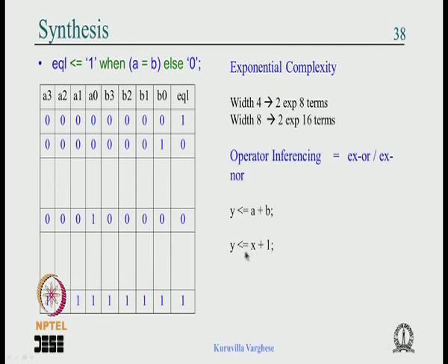Similarly, if you write x plus 1, this is replaced by an incrementer. So basically the synthesis works on the standard structures of the operators, it heavily depends on catching the operator which is used and the equivalent circuit written in the library for that particular operator.